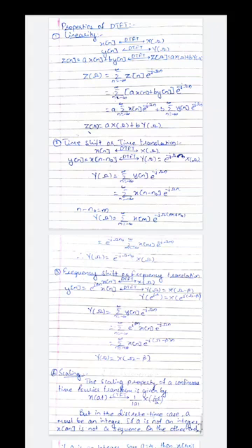The third property we'll be studying is frequency shift, or sometimes it is also referred to as frequency translation. Again, if x of n and X of omega are the transform pair, and this time if the spectrum X of omega is shifted to beta frequency represented by X of omega minus beta, and if this frequency shifted spectrum is represented by Y of omega, then its